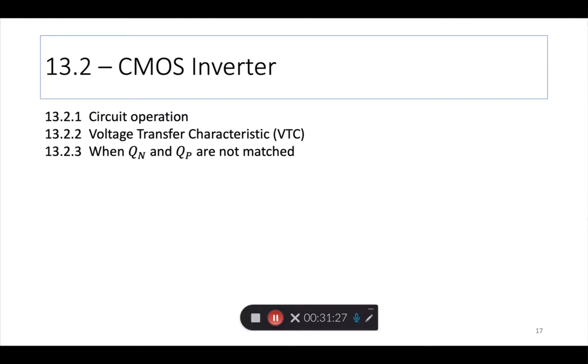Okay, so after having studied inverters in general, and inverters can be made up of one NMOS device, two NMOS devices, NMOS, CMOS device, a variety of options, right? But most of our work is focused on the CMOS inverter, primarily because of the advantage of low or zero static power consumption. So we have concluded that even though you have to put two devices every time, it's worth the expense. So at least for this chapter and what we are studying here, we will focus on CMOS.